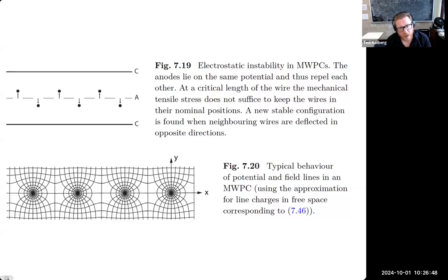There's some mechanical engineering that goes into doing this well. Obviously, if you want longer wires than 80 centimeters, you need some kind of insulating intermediate supports along the way to hold the wires in place so that they can't move out of plane. And the frame that goes around this whole thing needs to be strong enough to hold the tension on each wire multiplied by the number of wires, which can add up to a pretty significant force.